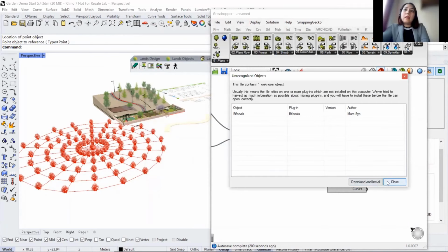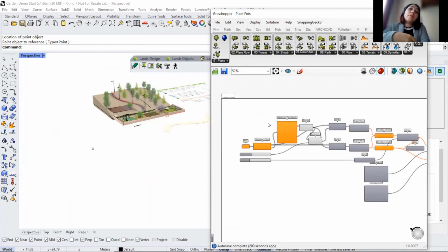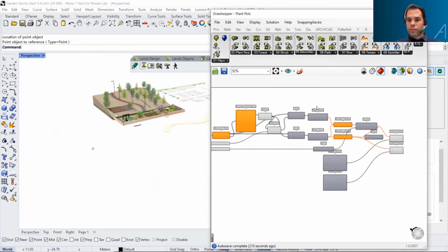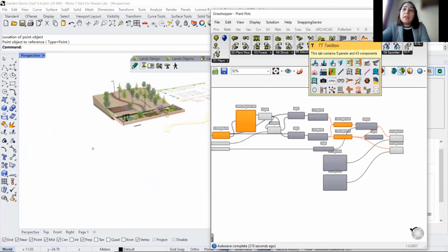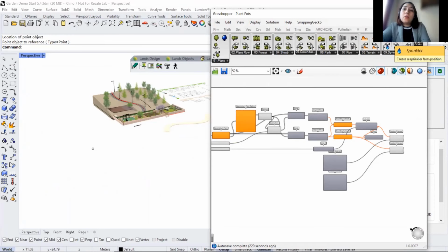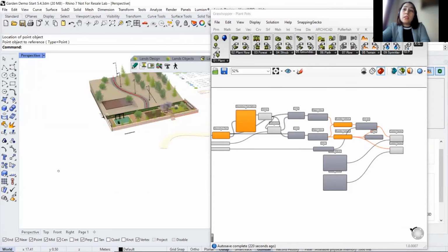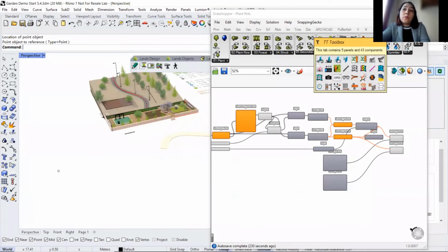Lucas is telling that they got the information from Surveyor, and then they start modeling, they start designing the landscape, and so they need to, or they can indicate XYZ of the document according to what they import from Surveyor. Or there is another option that he's also asking: set XYZ of one point of your project to 0 and start in Rhino.